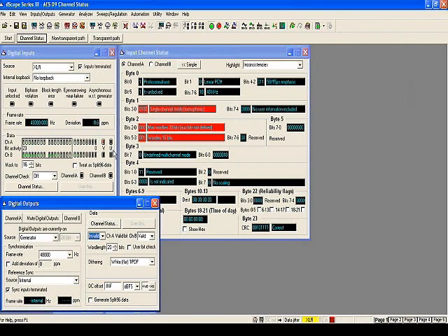The other thing you want to be able to verify is user bits. If I click on user bits here, you can see my user bits go green, telling me that I've got a transparent user bit data stream as well. I'll just shut those off for a minute. Now, let me get back to this validity bit for a minute.